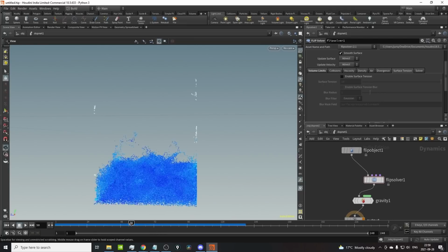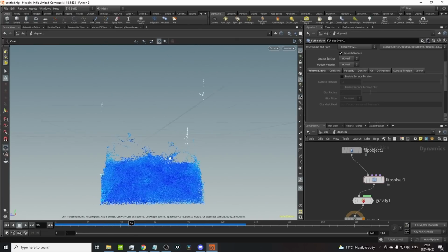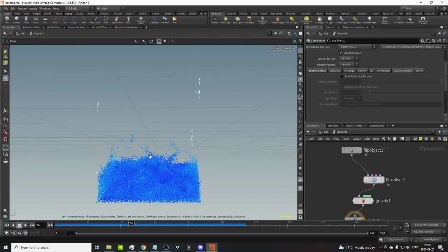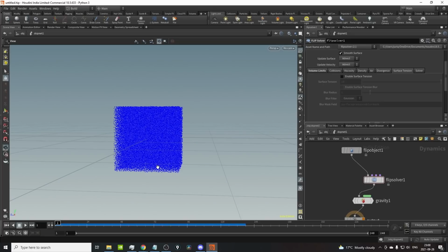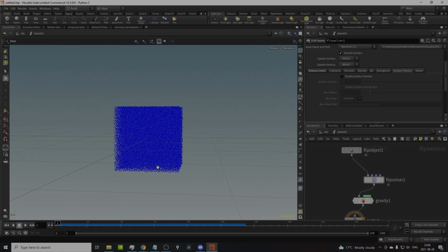For example, here was one nice one. It comes down and it splashes sideways like this. That's quite nice, but all of this area would be dampened because the fluid wants to hold on to each other, right? So forces to break out, generate those droplets, generate those splashes, need to be a lot higher to actually happen. So that's one downside, I guess, in some cases that you could keep in mind for surface tension. But in general, turn it on. It should add nice features to your simulation.